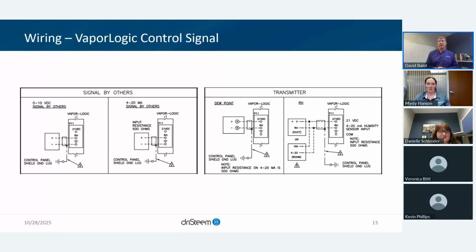Okay, great question. To answer your first question, the modulating high limit and the humidity transmitter are exactly the same device. It's a matter of where I connect them to and what we do with that information. So wherever we connect up to this, like we're looking at here on this screen, where we're putting that RH into P11, that is going to be used for demand purposes.